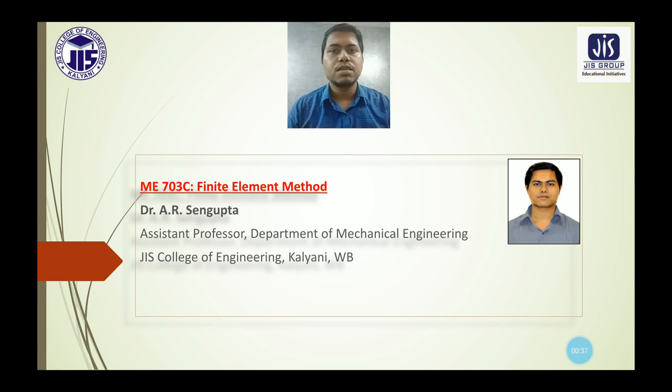Next, the concept of the axisymmetric elements was discussed in detail, and based on the different formulas of these axisymmetric elements we have discussed a lot of numericals. Regarding these axisymmetric elements we have seen the formula for the shape function, then the stress strain relationship matrix, then the strain displacement matrix, then the stiffness matrix.